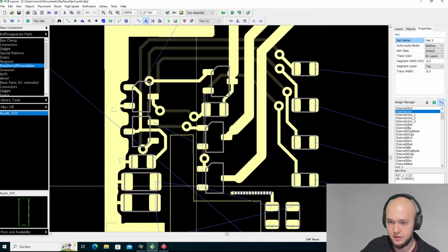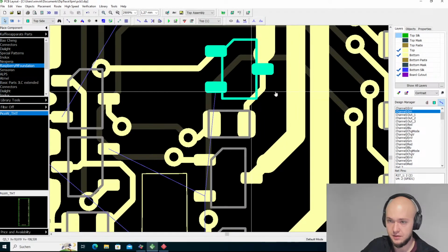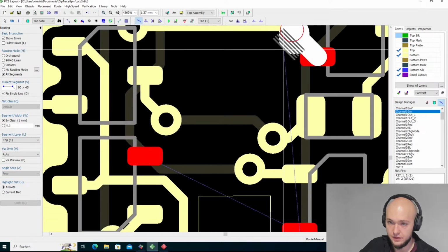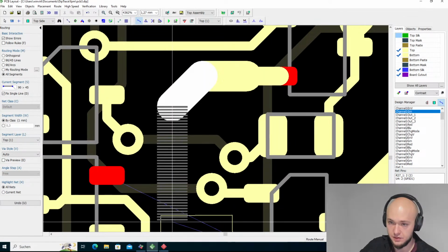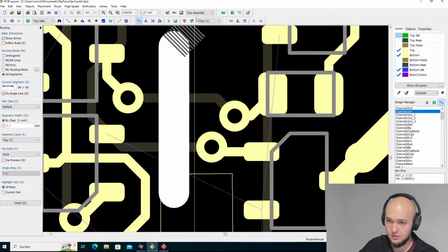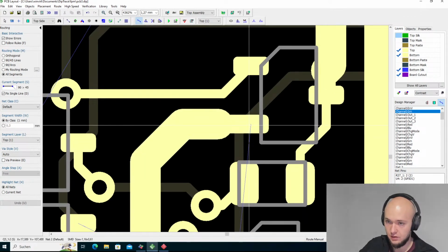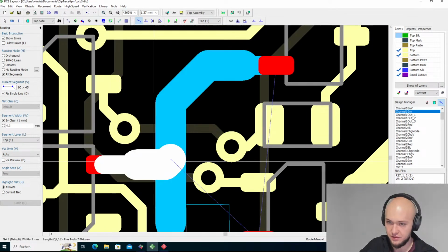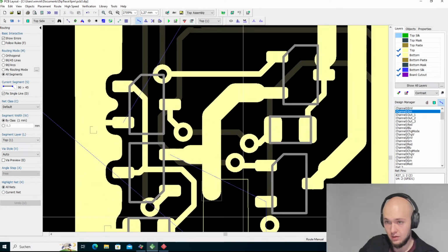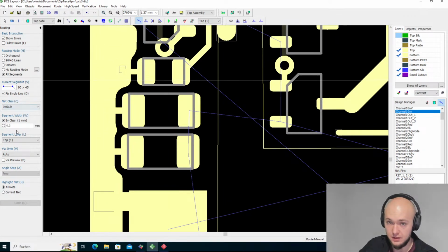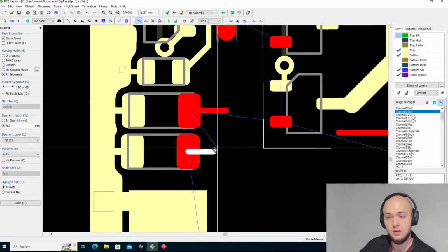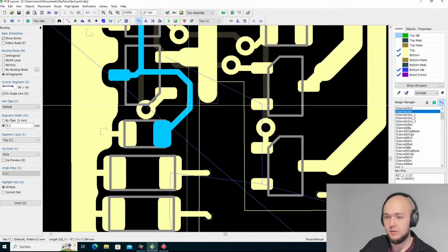all for that, because do we have anything here that needs to be connected? Yes. From this point we simply have a really big trace that goes up here, and it goes down. Because there's no reason to have some ground plane up here. There is no reason at all. Down here we will have relatively small wires because I don't expect to have such big currents up here.